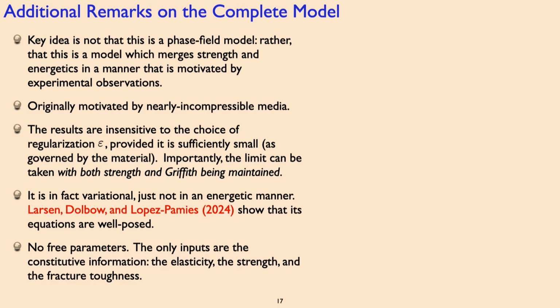It was originally motivated by applications of some of these models to nearly incompressible materials, right? And this motivates why an energetic model, purely energetic model, is problematic, okay? Because if you take a nearly incompressible piece of material and you subject it to a hydrostatic state of stress, it can't deform, right? Because it's nearly incompressible. And so it can't build up any strain energy, right? And so purely energetic models predict that you'll have failure at an infinite value of the pressure. But again, real materials don't respond that way, okay?